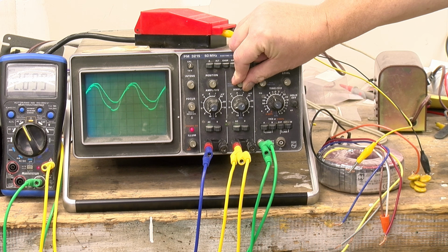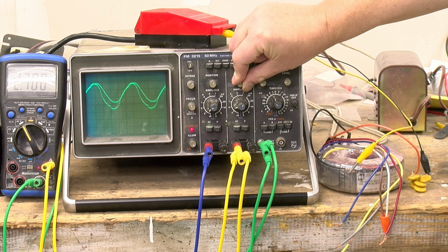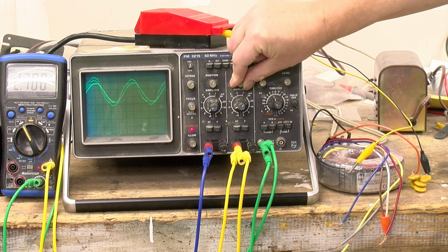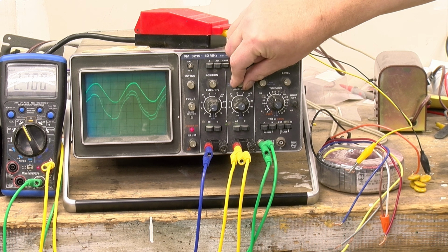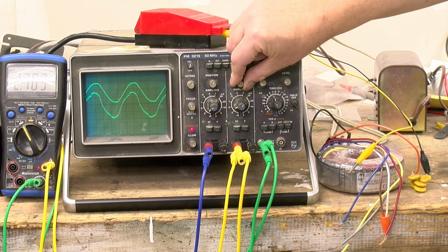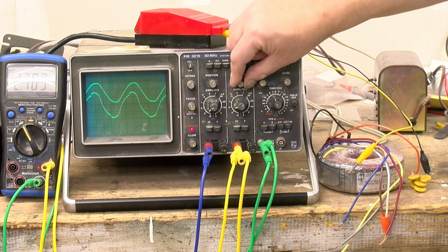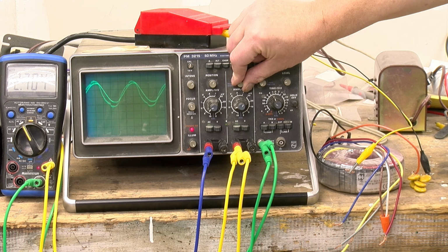We can bring this current one up so we can compare it with the AC input, and sure enough, they're pretty close. We haven't succeeded in completely making them in phase because those capacitors are all of a limited size, 0.01 microfarads, and I was adjusting it by adding more or less of them.